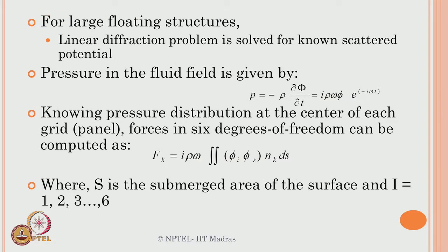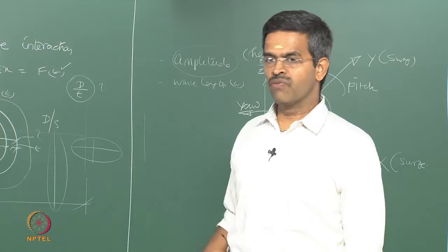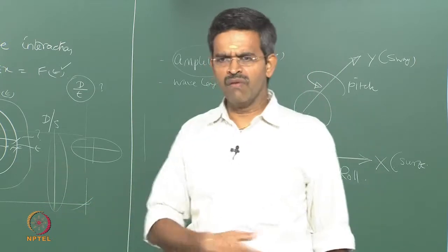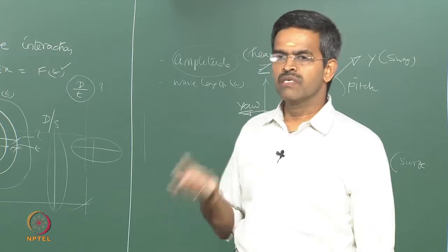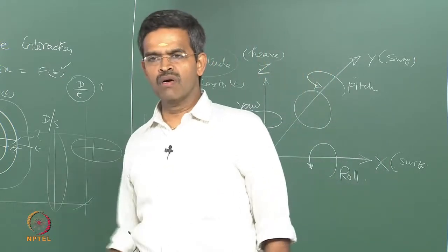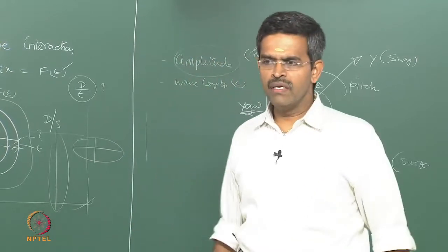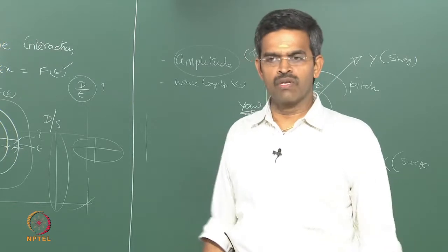Now, on the other hand, this will not suit large floating structures because it becomes a problem. Please understand, when I say large floating structure, it is not largeness because of the diameter of the member; the structure itself is very large. So, the buoyancy force or the surface area occupied is very large. For example, FSRU, floating storage regasification units, are very large in size, 190 meter long, 45 meter wide, and the design draft can be about 23 to 25 meters. They are very large floating systems.